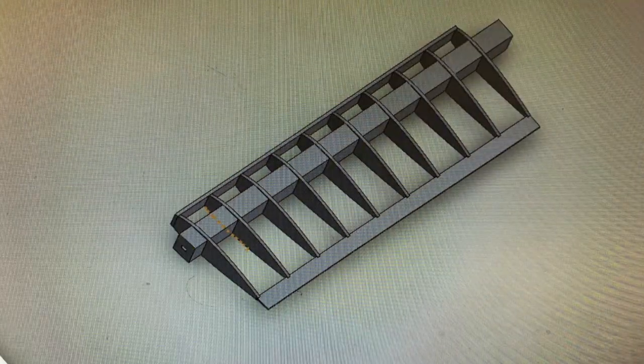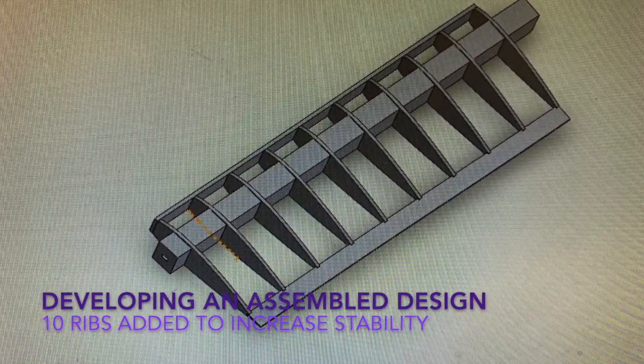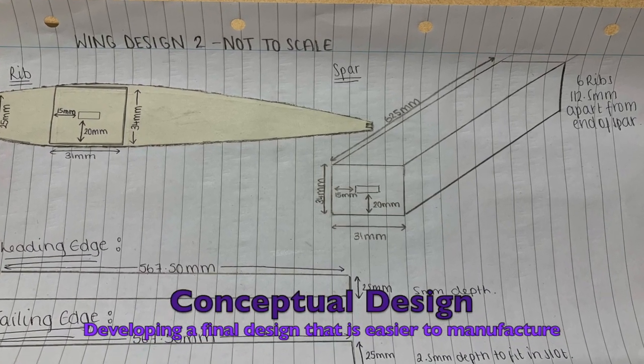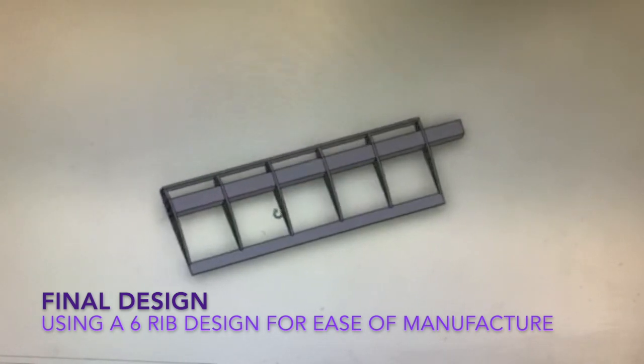Assembly of the final design was created in SolidWorks and a 10-rib design was selected by the group. However, for ease of manufacture and limited time constraints, a 6-rib design was finally decided upon, and slots used in the ribs meant that the trailing edge would be easier to fit.